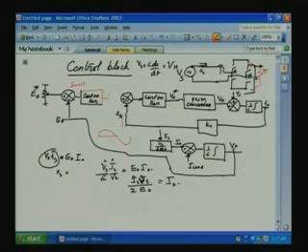We need a multiplication block. I will make it like this. It's a multiplication block. You give this one here, and this one you should give here. The output should be given here. So, this sin omega t, which is in phase with this one, will ensure that the current drawn, IS, will be in phase with Vs all the time, and you have to generate VR.